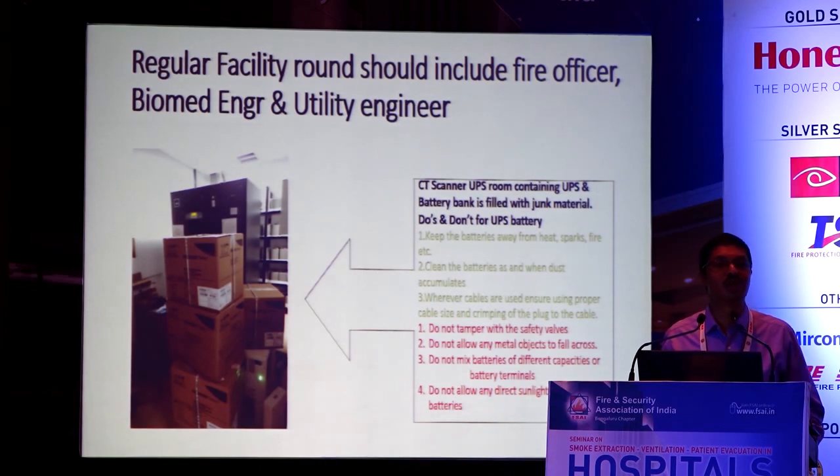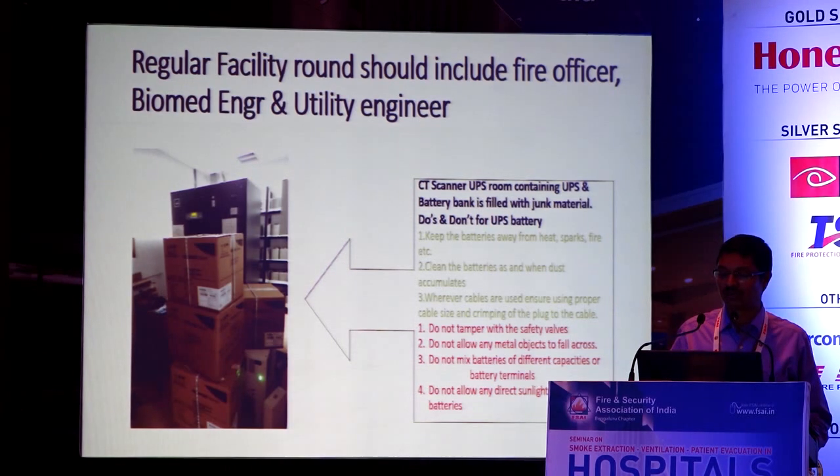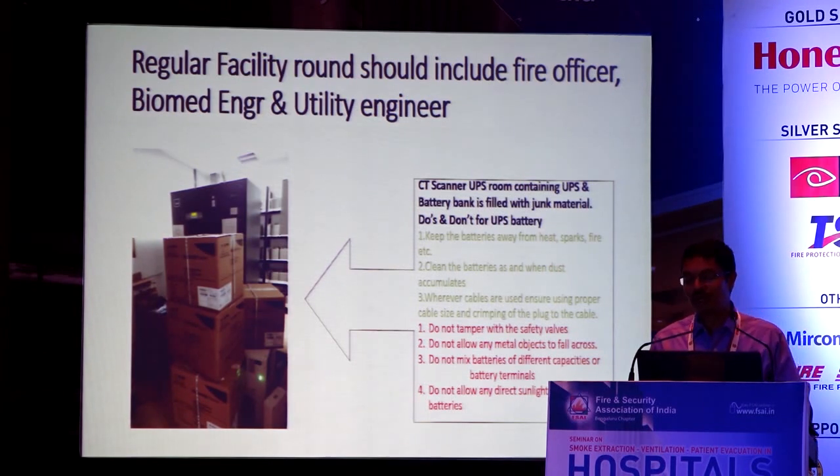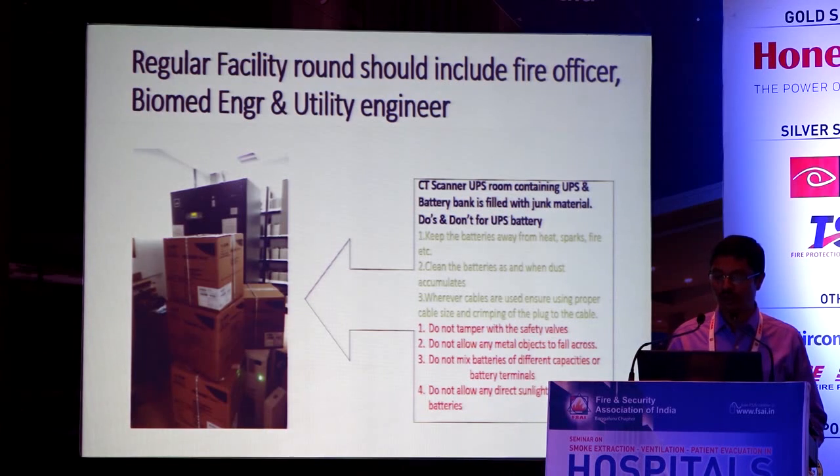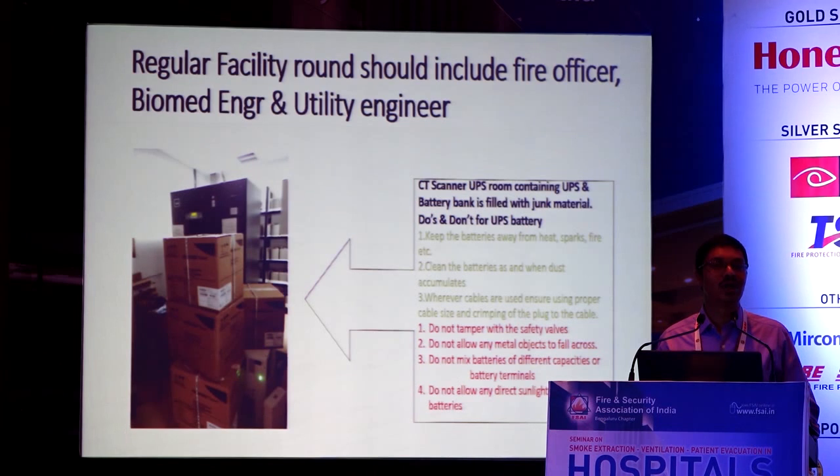Some do's and don'ts for the UPS batteries. Keep the batteries away from heat, sparks and fire, clean the batteries, and ensure that the cables are of proper size and clamped properly. Do not tamper with the safety walls. Do not allow any metallic objects to fall across. Do not allow direct sunlight. In a hospital there are the central UPS as well as the UPS used along with the medical equipment. Please ensure these are taken care of properly.